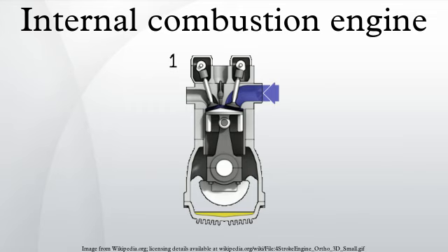Gasoline ignition process. Gasoline engine ignition systems generally rely on a combination of alternator or generator and lead-acid battery for electrical power. The battery supplies electrical power for cranking, and supplies electrical power when the engine is off. The battery also supplies electrical power during rare run conditions where the alternator cannot maintain more than 13.8 volts. As alternator voltage falls below 13.8 volts, the lead-acid storage battery increasingly picks up electrical load. During virtually all running conditions, including normal idle conditions, the alternator supplies primary electrical power.